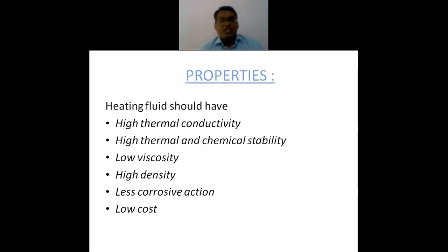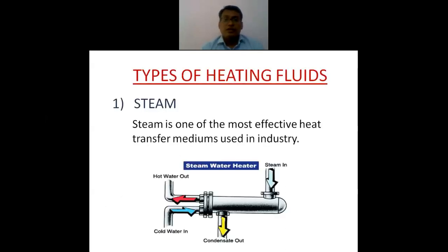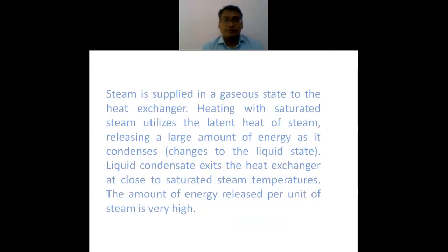High thermal conductivity, stability, low viscosity, high density, less corrosive, and lower cost are needed as the properties for a heating fluid. This is steam, which is one of the most effective heat transfer media used in industry. Steam is the cheapest one. Hot water is still cheaper. Again, that depends on what temperature is needed.